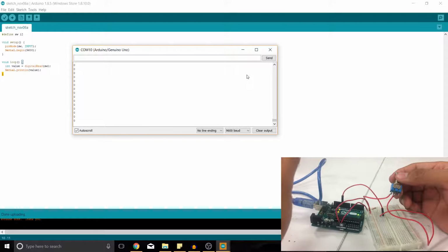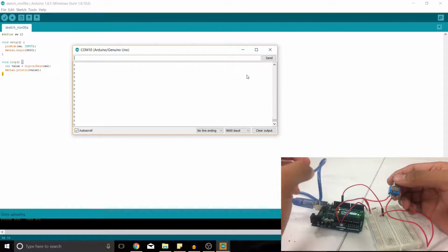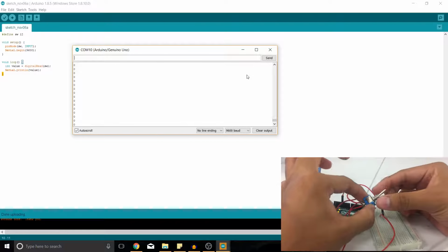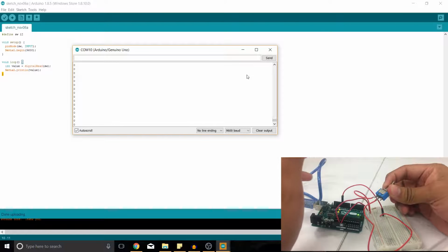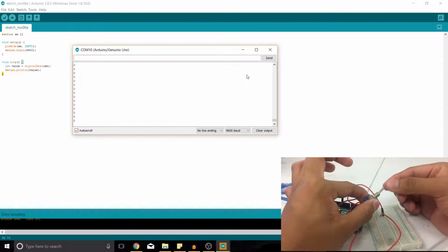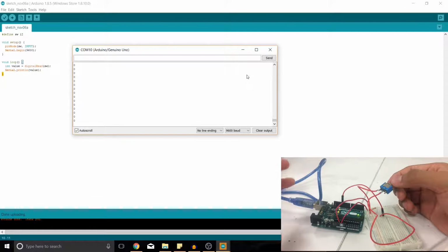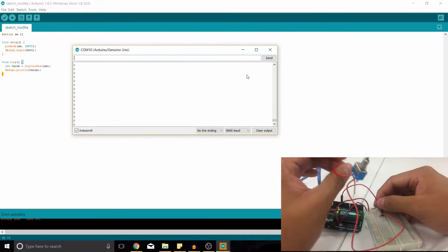But if we want to do what the title of this video says, and the description, if we want to control the speed of a motor, I mean, yeah, this controls the speed, it's on and off, but if we want to regulate the speed, we're going to need something different. So now we're reading 1 and 0, but what if we could read a range of numbers, let's say 0 to 1023? Well, the Arduino can also do that, and we're going to do that right now.